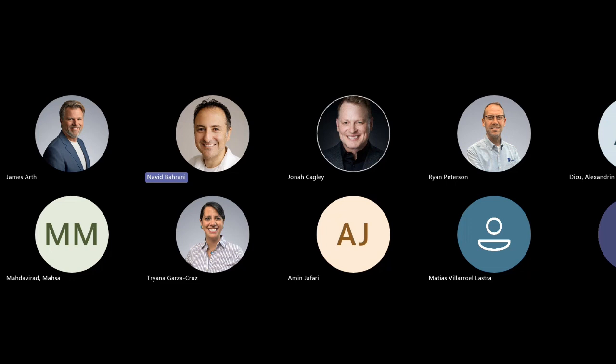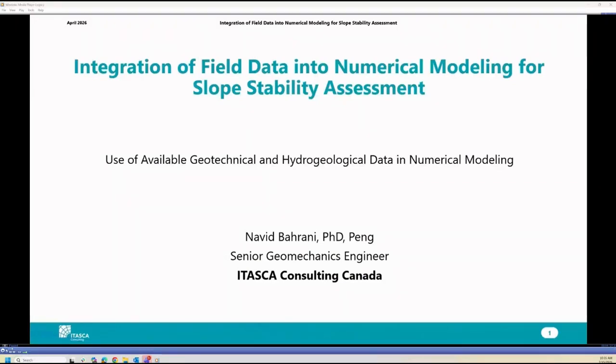Yeah, that's a good question. So IMAT is Itasca's mining analysis toolbox. The engine is FLAC3D, so you can basically create a FLAC3D model using IMAT. It works based on octree zones, meaning that all the zones are cubes. We can build that model entirely in IMAT, and we can import any kind of data. We can adjust the properties to calibrate the model based on field data, and we can analyze the data. So everything that you can do in FLAC3D, you can do pretty much in IMAT as well.